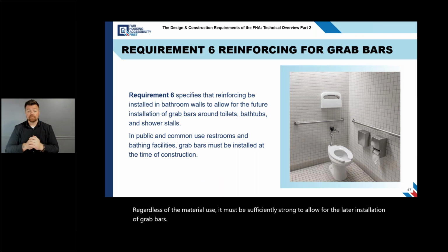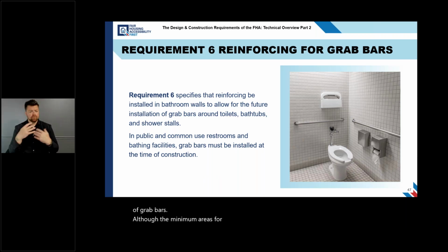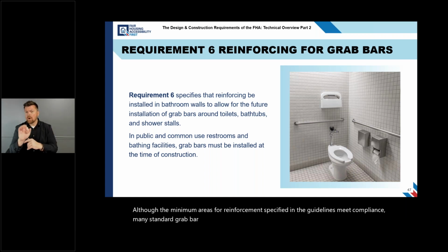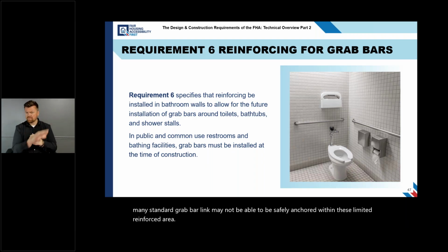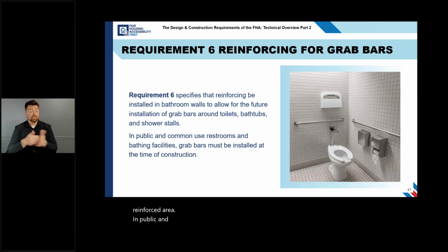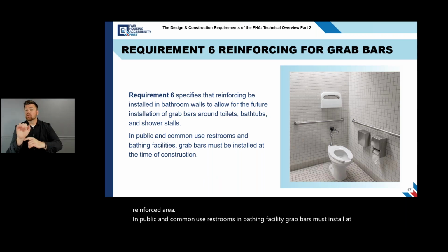Although the minimum areas for reinforcement specified in the guidelines meet compliance, many standard grab bar lengths may not be able to be safely anchored within these limited reinforced areas. In public and common use restrooms and bathing facilities, grab bars must be installed at the time of construction.